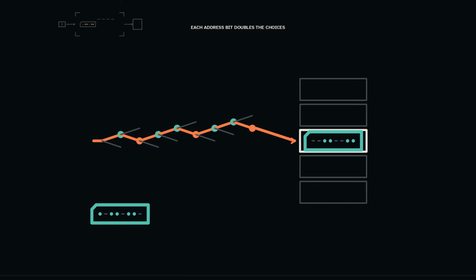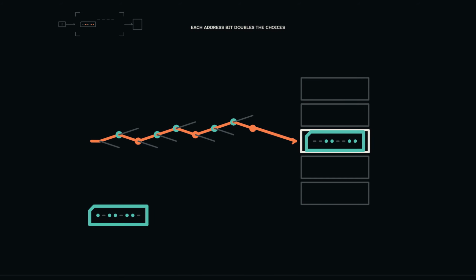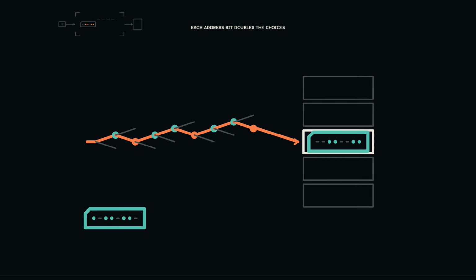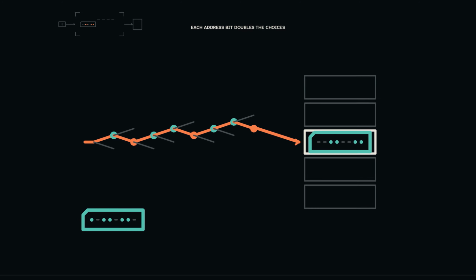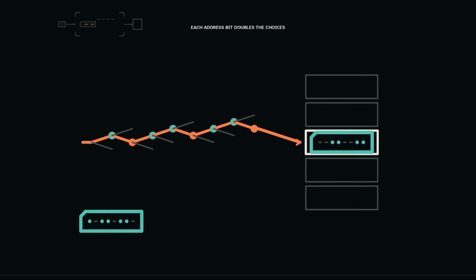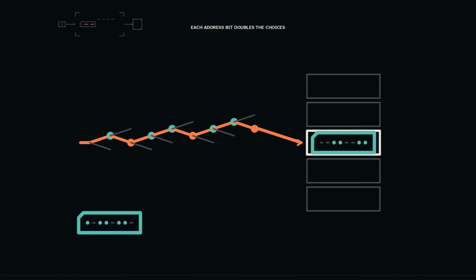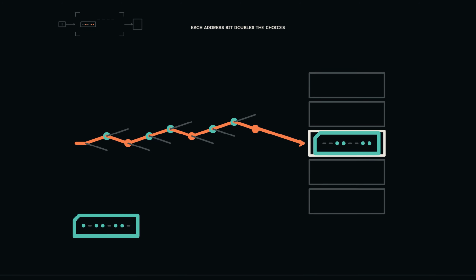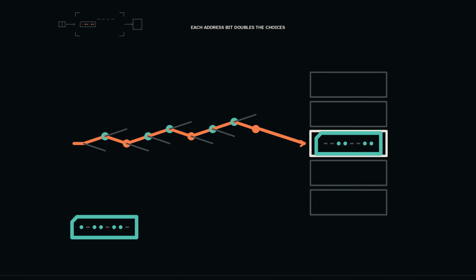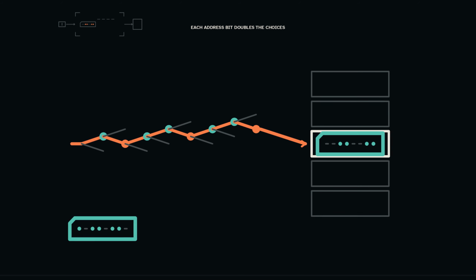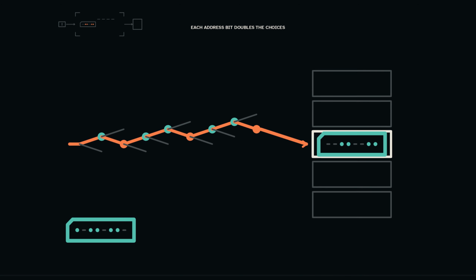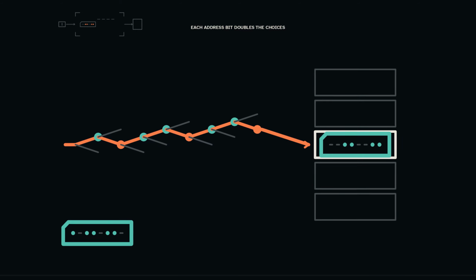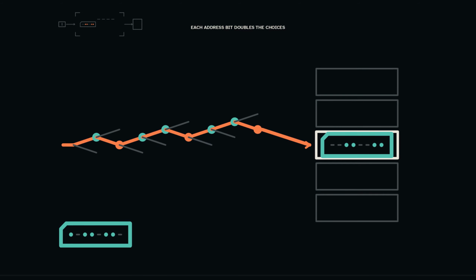SE8 uses 8-bit addresses, so its address space contains 256 byte positions numbered from hexadecimal 00 through hexadecimal FF. Hold address pattern 101-10110. Its active weights are 128, 32, 16, 4, and 2, totaling 182, or hexadecimal B6. Before the decoder reveals its outputs, predict the invariant. Output B6 becomes active and every other output remains inactive.